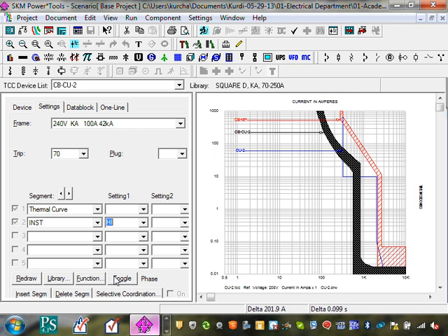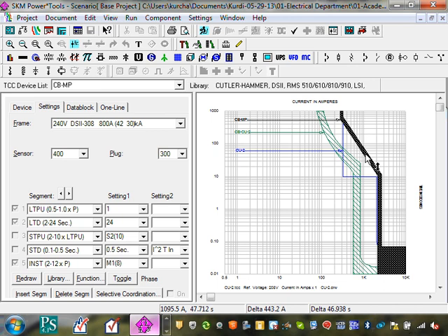And as you guys know, we use the adjustable instantaneous because of the inrush of these motors. So it allows us to adjust the instantaneous to avoid nuisance tripping when this equipment energizes because of their inrush. But still cheap. So you're looking at a fixed circuit breaker with an adjustable instantaneous, and the second one here is a fully electronically adjustable circuit breaker.